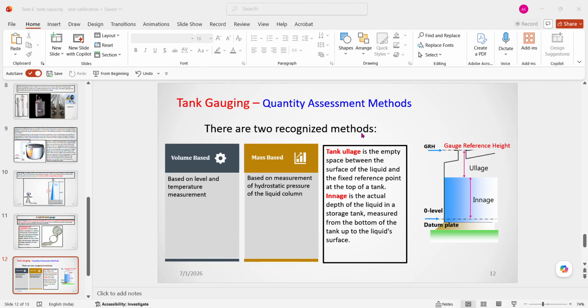Then radar. Radar is very important, because I have told you, if any fluids are very corrosive, no mechanical item can be used. There radar will give the signal. Radars are highly reliable, non-contacting devices that measure the level of the liquid or solid in the tanks and silos, and they emit microwaves. This will give you the microwaves.